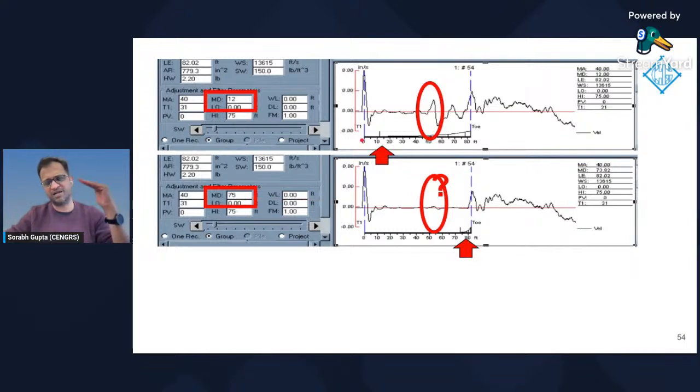Remember I told you how the magnification is an exponential curve, which is multiplied by the data to open up or stretch the data at deeper depths. What I did not mention is that usually we use MD, which is magnification delay, and a magnification delay of 12 feet means that the magnification multiplier starts from 12 feet.